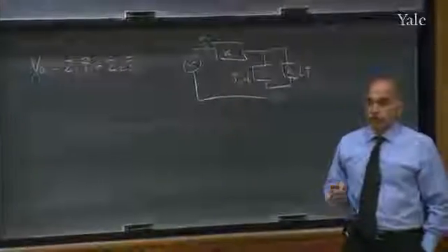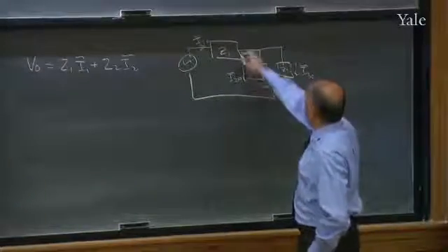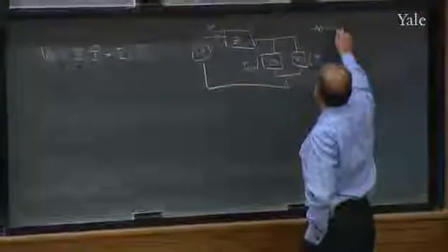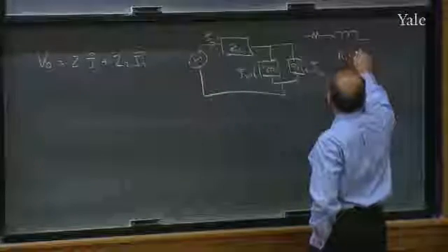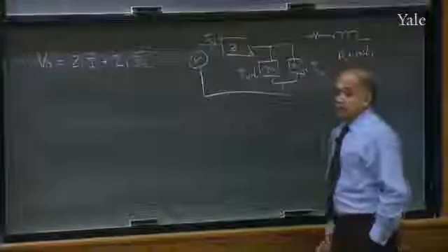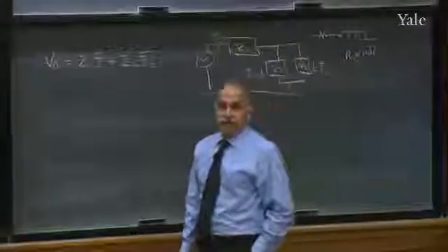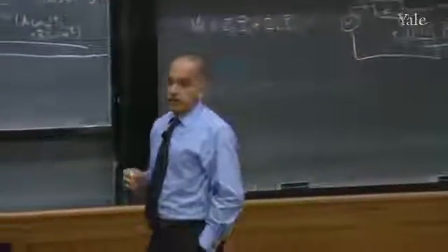And the rule for impedance is very simple. If you open the box and you find a resistor plus an inductor, the impedance for that is R1 plus I omega L1. That's it. Apart from that variation, it is just like a DC circuit.